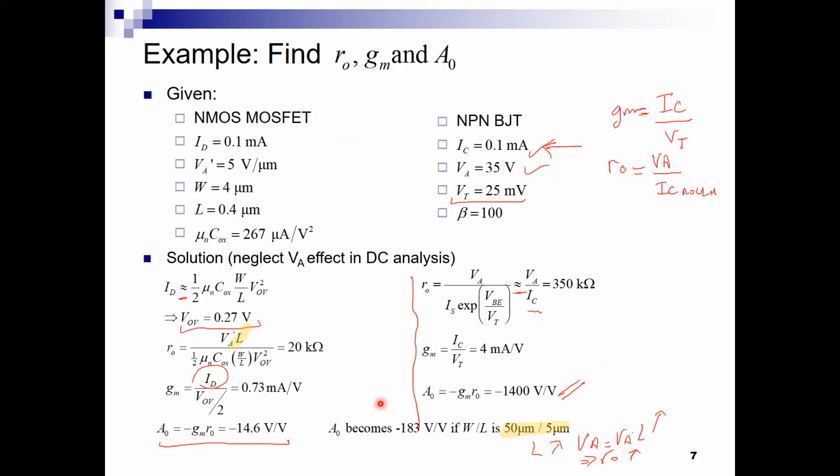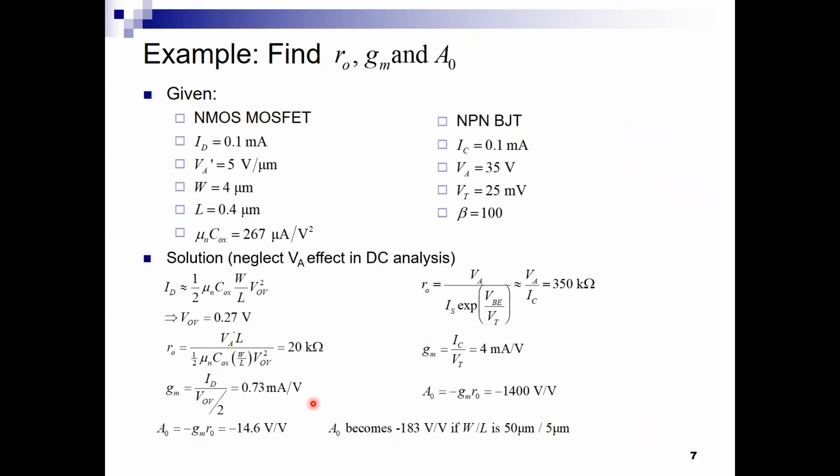So if we're keeping the ratio the same for W over L, why don't we increase it even more? Is there a cost trade-off or something? The area of the transistor, if it occupies too much area, then your design will have a cost in terms of you cannot plug in other designs with it. But okay. Typically, yes, if it is something critical, you can size it differently. Okay, great. So now this is the example on the intrinsic gain of the MOSFET.